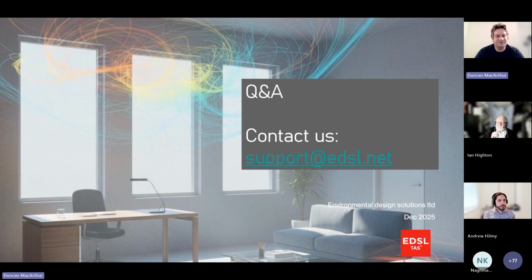You're trying to beat the notional, so a lot of the time you're saying, well, the notional uses demand control, so if I'm going to reduce my auxiliary energy, I need to use demand control. So I would do that first in the studio, and then I would work on my design outside of Part L if I was going to optimize anything.